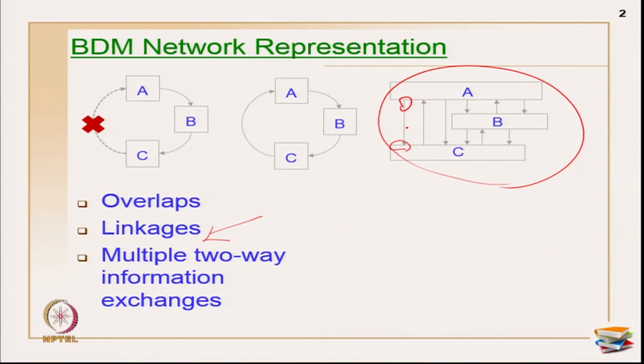For this particular linkage, A is a predecessor and C is a successor, and I can start anywhere in the flow and I can stop anywhere. So it is not following the conventional finish start, nor like PDM representations wherein you show start start, finish finish, start finish and so on. It actually directly connects the predecessor and successor at the relevant points.